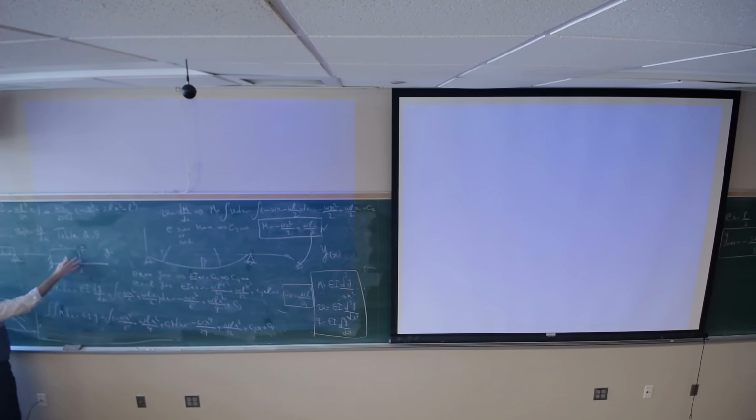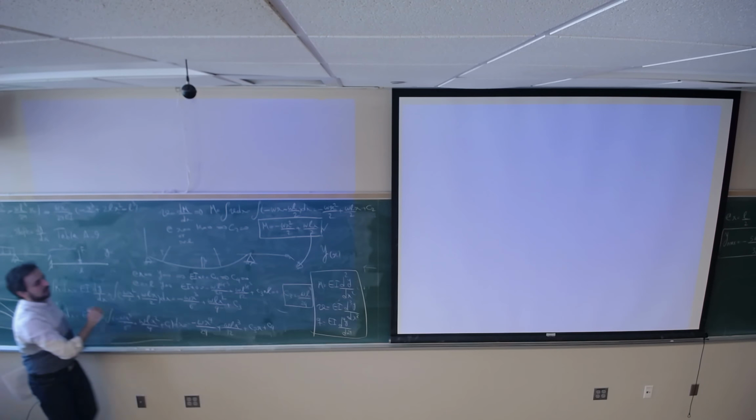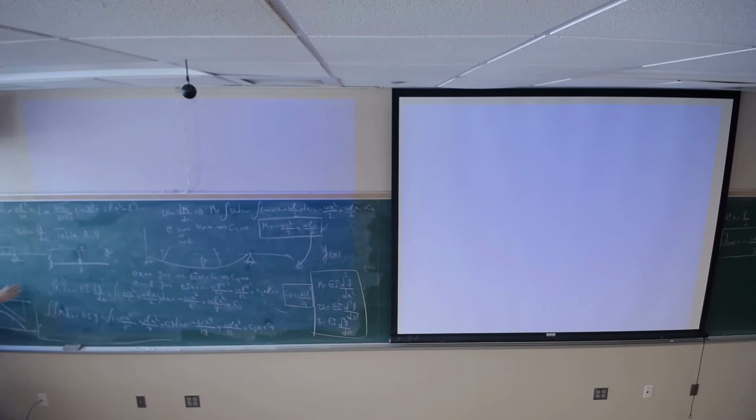But I can ask you to derive the deflection function for this loading and this beam. You should just use the same approach that we did: derive the bending moment, then do the integration twice.